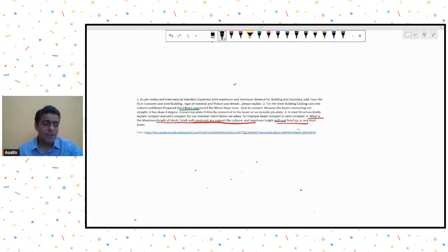So in such cases, there are some guidelines given about the ratios to be followed for the brick wall height to its thickness. So there is an Indian standard for structural use of brick wall. Although your brick wall may be part of your partition wall, you can still refer to that code. The number I'm forgetting, but it is about the structural use of masonry. If you search it on the internet, you will easily find it. I'm not able to remember its name right now.